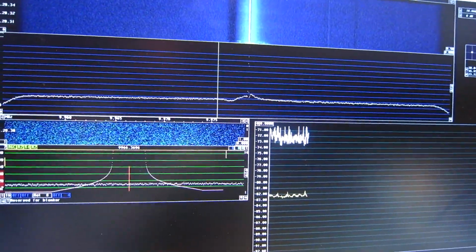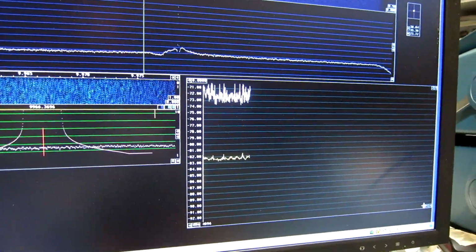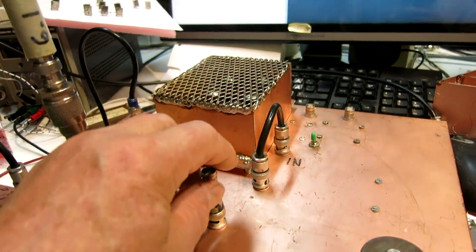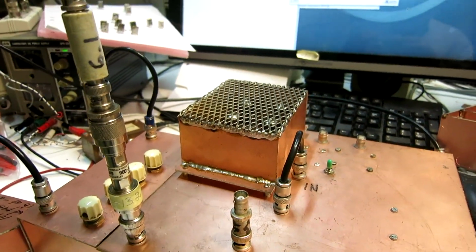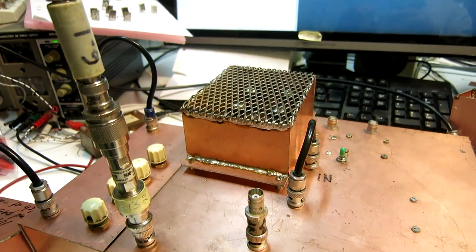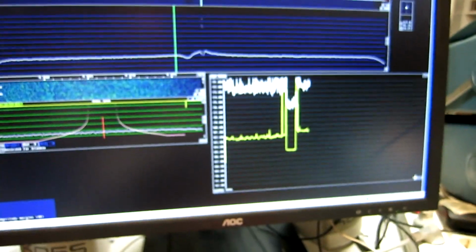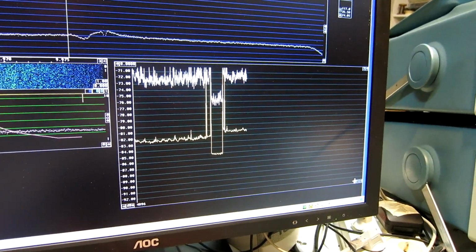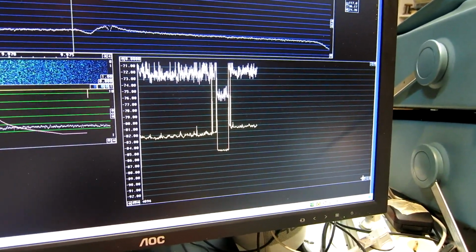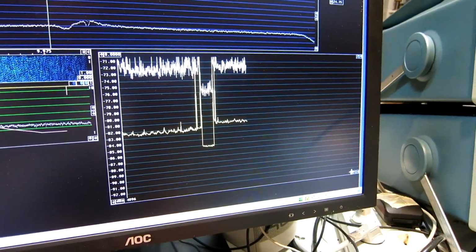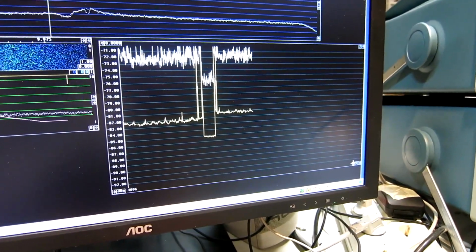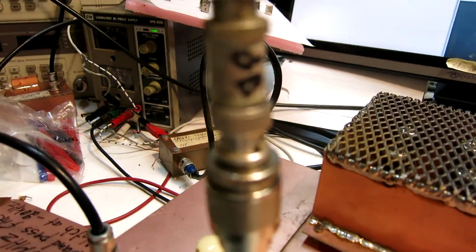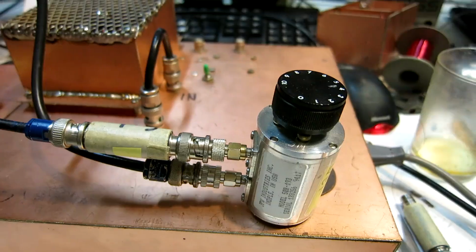I'm looking now outside the notch with the S-meter, and I take this 2 decibel attenuator and insert at the 0.5 dBm power point. It attenuates by 2 dB, so one should expect a lower noise, but the noise increases by about 1 dB. So this one is also a noisy attenuator.